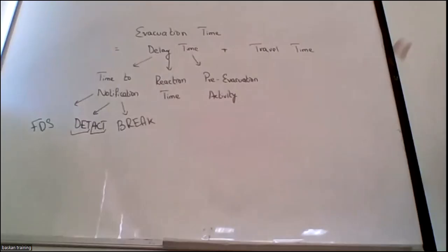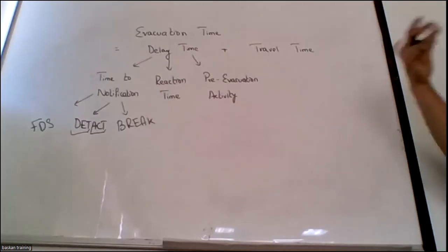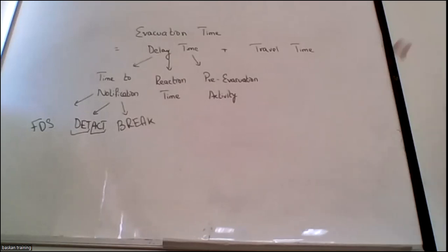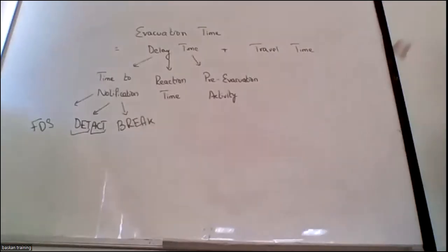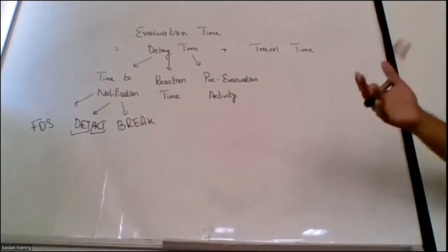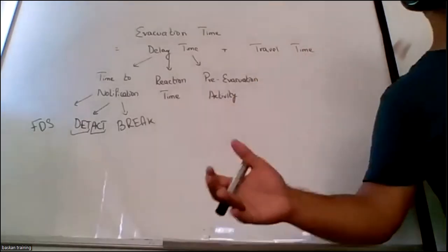So whenever a designer, the hazard recognition specialist, is designing the egress, he has to keep all the parameters intact. In the previous lecture, we were discussing the disabled occupants also, and that is the scenario that we have to always keep in mind. Whenever we are talking about residential occupancy, it is not only the healthy occupants that we have to consider, we have to always consider the disabled occupants also, and how they are going to evacuate.